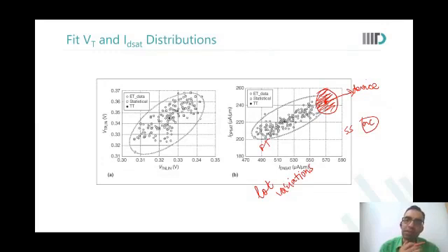So even for a lot, there will be other device variations which come into the picture. So how do you validate those? One part of validation, we said, is that we will characterize and design our circuits at SS, 1.1, 125, that is SS, low voltage, high temperature, and all that. We just agreed that we will do that. But for final circuit verification, you also need to take into account device variations.